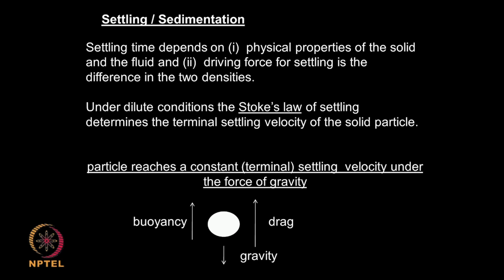The settling time of the solid in the liquid depends on the physical properties of the solid and the fluid, like densities, viscosity of the liquid and so on, and the driving force is the difference between the two densities. So, what is the law which governs this solid liquid separation in sedimentation, which is also called settling? That is called the Stokes law. It is very simple, but it is quite powerful in doing certain calculations. We will look at some problems as we go along.